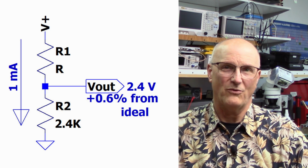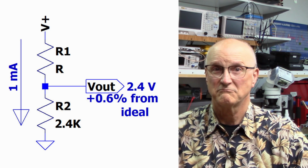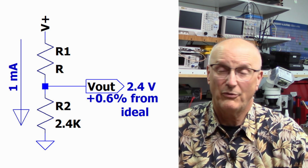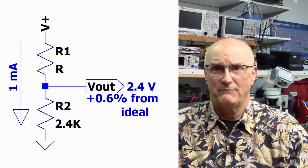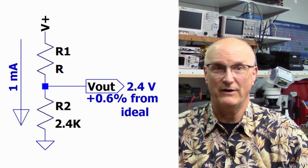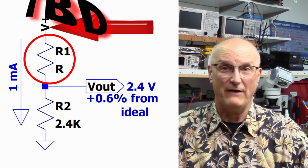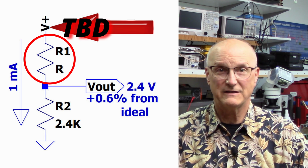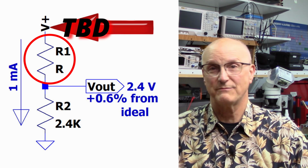And you say, okay, why did I choose 2.4K ohms over 2.37K ohms? I don't know, because it feels good to me. The voltage will be a mere 0.6% away from our ideal regardless of which one I choose. And besides this, there's nothing precision about the operation of a peak indicator LED. The input resistor depends on the power supply voltage, and we haven't determined what that will be yet. We will have to choose the input resistor value for this voltage divider once we get to the power supply portion of this design and know our supply voltage.